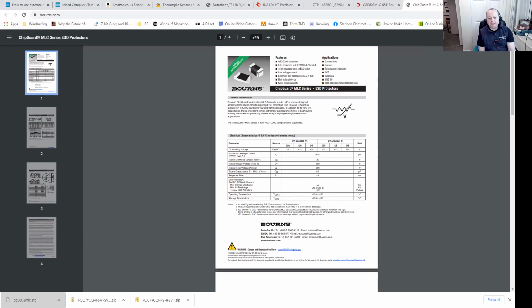But for stuff you're designing with your Arduino and your Raspberry Pi and your ARM cores, stuff I'm doing, I've looked into it. I've done track length balancing, and occasionally I've forgotten about it, and it's not made a scrap of difference. So if you're going super high speed, and I can't see why you would be, unless you're getting into memory management for your little logic circuits, I wouldn't worry about it. Okay, sounds good. It's nice not to have a problem, isn't it?